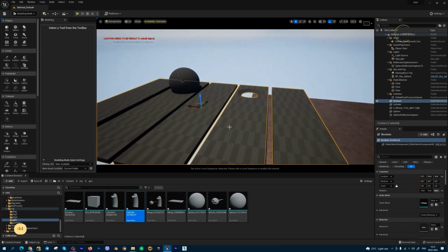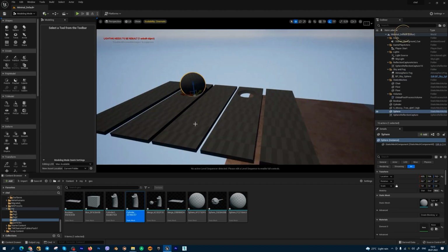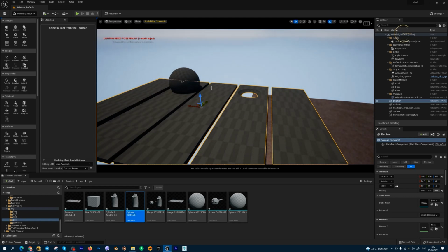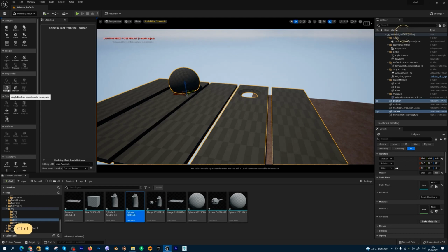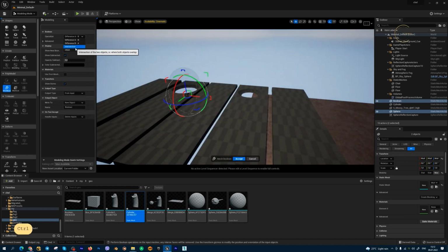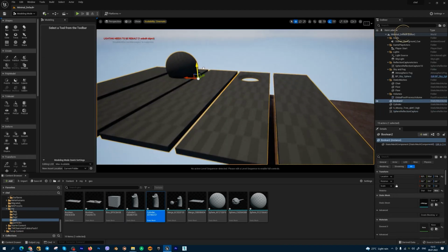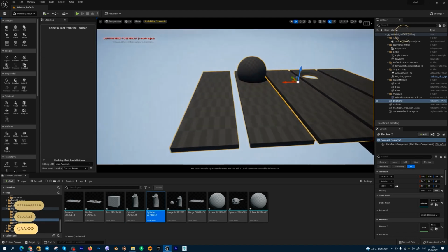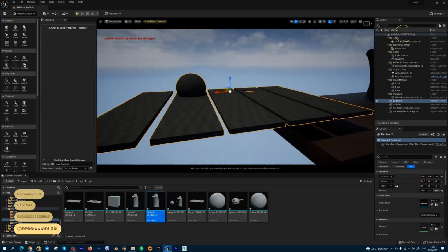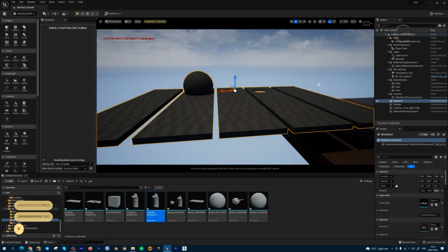Next press accept. And we can select another object to make a hole from this sphere. Also we can attach all your boolean meshes, for example all your spheres, and create one operation for all attached spheres. I can select first my object, this A object, then select the second object, press boolean, and in this case we can, for example, do union to attach one object to another. So we get one separate object, and we can start working with the UV coordinates of this separate object.